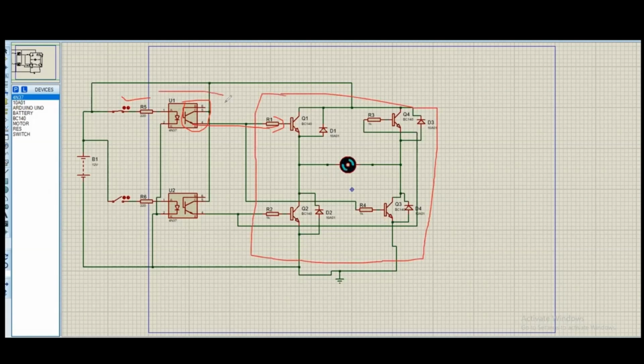Only the difference is these optocouplers and this switch. First this LED turns on, this one and this one, and then the phototransistor in front of them will also get turned on and make this collector and emitter short. You can see that the collectors of both optocouplers are connected to this source directly from this node here, which is providing all of the power to them.